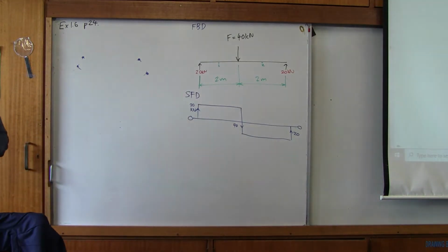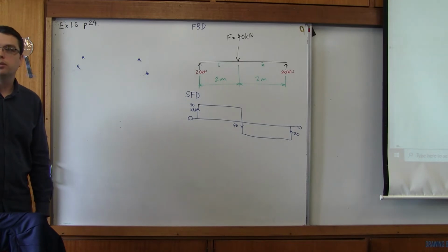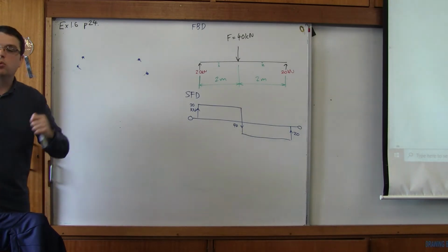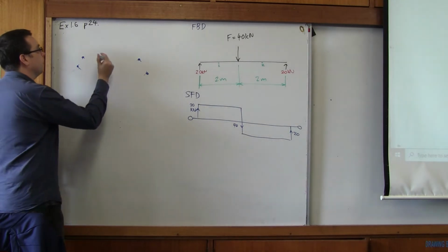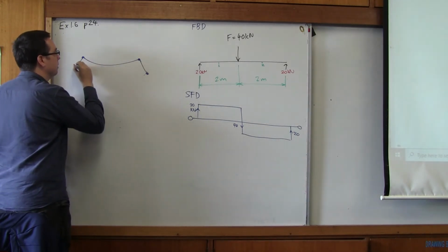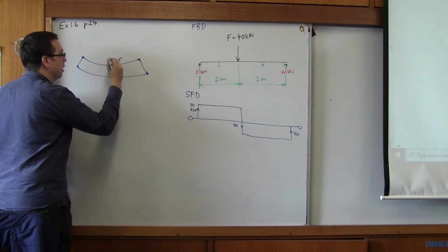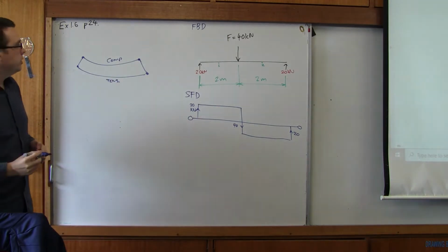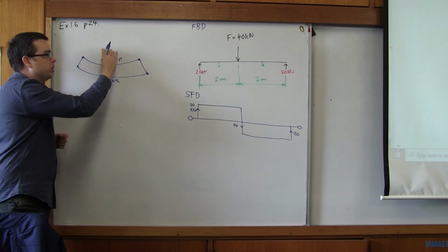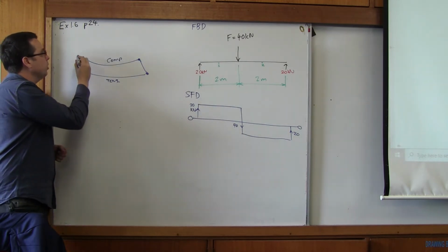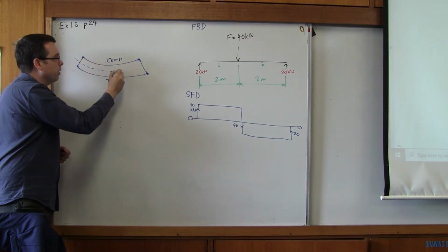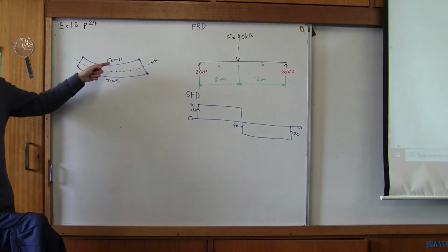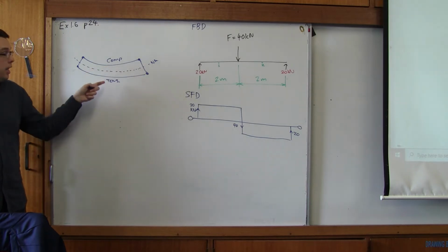Okay, the dots at the top, are they closer or further away? Closer. Dots at the bottom? Okay, when things are squashed together, what do we call that? Compression. Yeah? So compression, and at the bottom? Tension. Tension. Okay, so what we know is that we have this area of compression and tension. Now, the next thing we need to look at is somewhere in the middle here, we have this line where here it's being squashed a lot, and here it's in maximum tension.